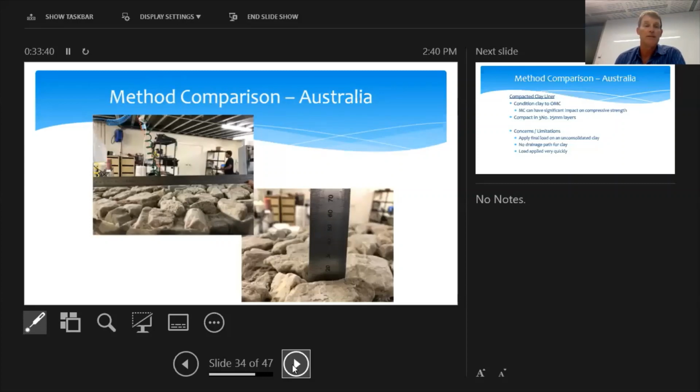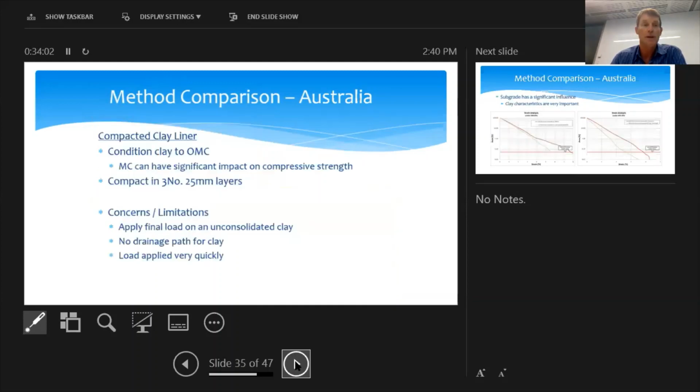What's important about this method is what you can see is that the top surface of that gravel is level and straight, and that the voids between the rocks are at least the thickness of the geotextile that you're using to provide as a protection layer. So the geotextile isn't supported by resin within the rock profile.